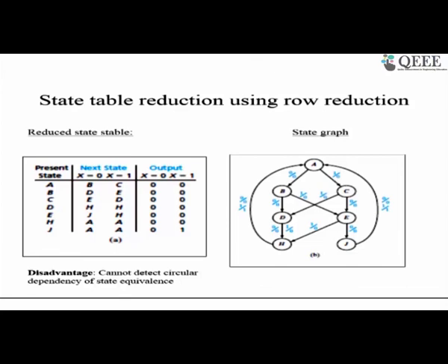Is there any comparison between a register and an FSM? Registers are a set of flip flops storing bits, but finite state machines have a register which stores the state. In addition to that, it also changes the state based on the input and output, but registers simply store the bits that we want to store. So every finite state machine has a register, but a register alone cannot be an FSM.